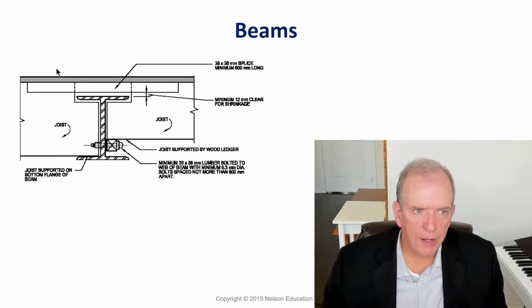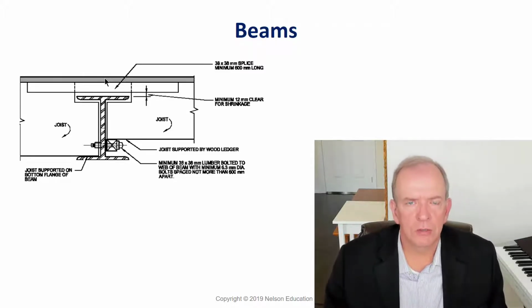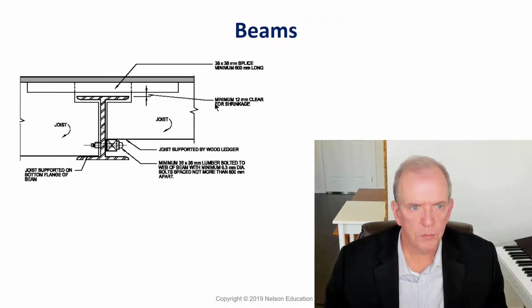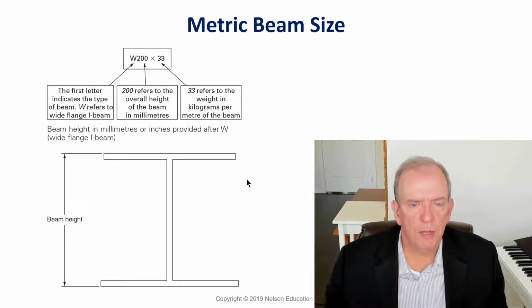And what if you had ceramic tile? I've seen this a number of times on top of there. The ceramic tile will crack right along there. So this conscientious carpenter actually caused a big, expensive problem in the floor, because usually you can't match the ceramic tile. You've got to get another ceramic tile and do the whole floor in that section, and it's not nice. So what you want to make sure of is that you leave a space around here and a space around here so that there are no shrinkage issues, and if it does shrink down, it won't have this pushing upward on that.